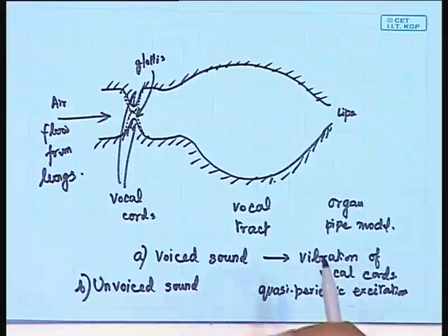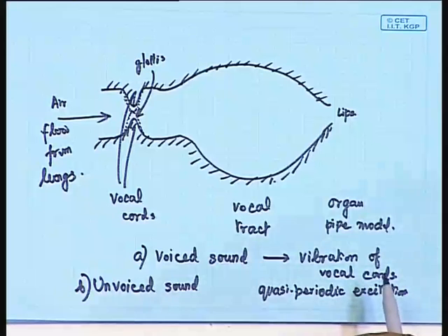So, that is what I was also telling you, that the entire speech processing model is so dynamic, okay, it changes with time, and it is only a quasi-stationary behavior that helps us in producing a model. Because there is a quasi-stationary behavior, we can have short-time speech analysis and at least try to extract the speech parameters, okay.